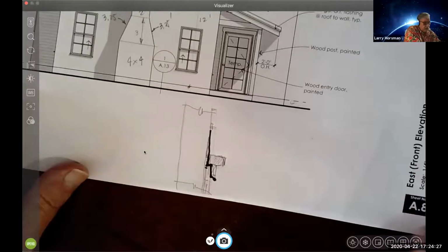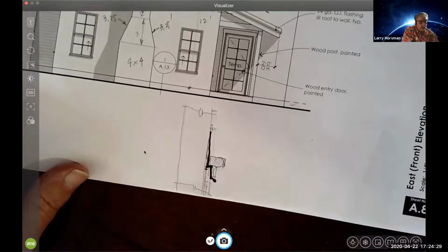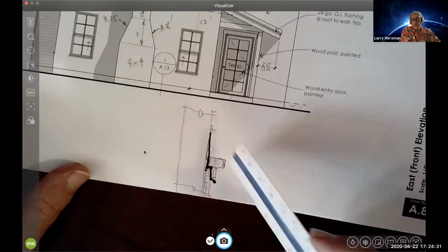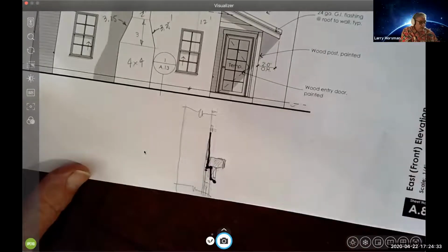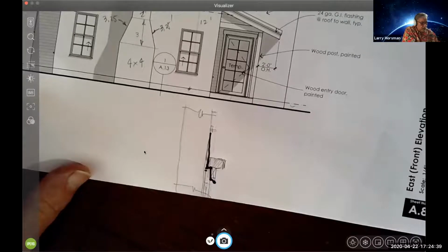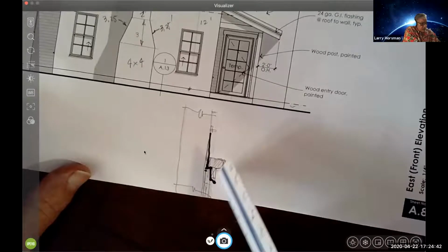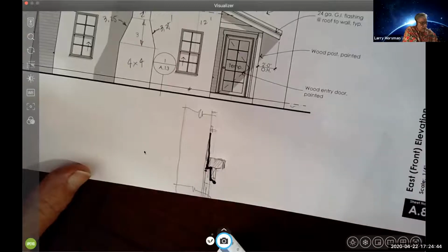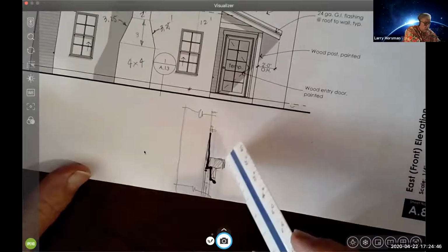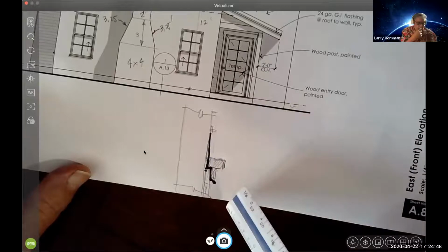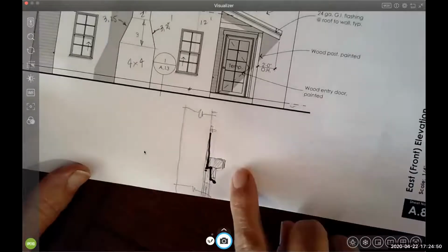Where this would be the flashing, and then I'd run a little bead of caulk right along there. That's probably how I would approach that, just to keep water from getting up and behind or in the stucco. If I try and put flashing out here and run it just to the edge, the water will run back under it, right? And get into the crack.